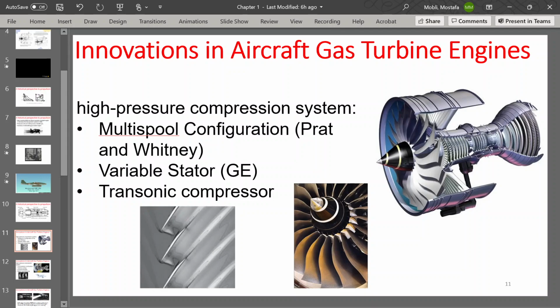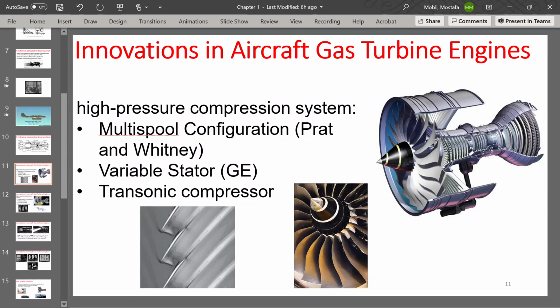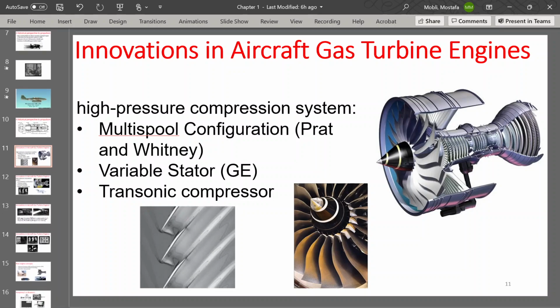You can control the stall, right? That's the idea, which essentially means that you can operate this compressor at higher angles, right? But the angle that your compressor sees is going to be lower, right? This is an important thing. So that is one of the things that I wanted to make sure we discuss about the variable stators.